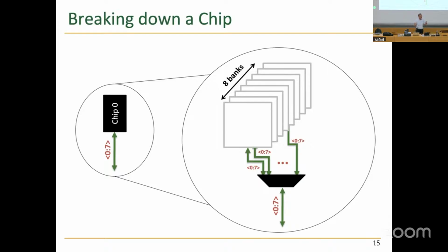That's expensive. So normally, DRAM chips are built by sending one address and one command to a particular bank at a given time. Then you start access to that bank. And then in the next clock cycle, you can send the other address to another bank. This way, you don't need to support more address and command pins than needed for one bank.